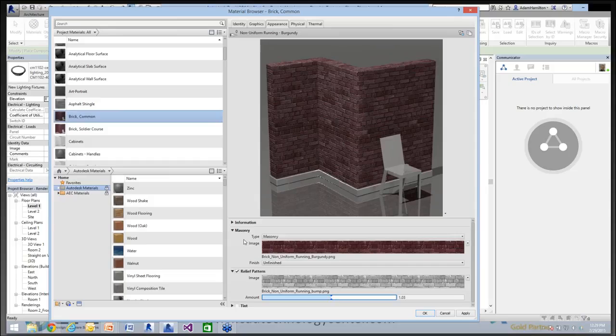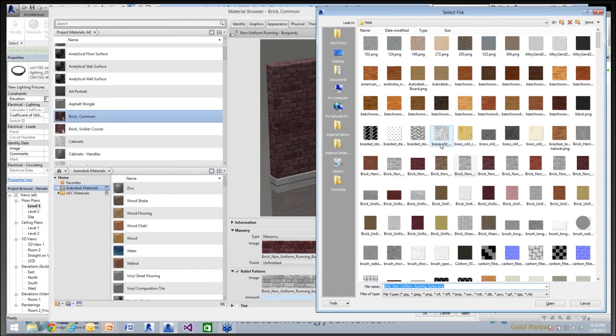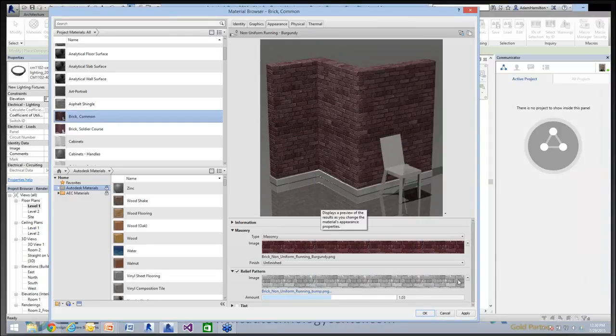And so take that image, and then you'll see the bump. And again, Revit has the default map libraries, material libraries have bump maps in there, and you'll see them tagged with bump. Okay, you see this one has some of the same setups, so the bump map for a lot of these. And that'll give it the texture. So Revit has some of these built in, by the way, but if you need to build your own, you can utilize that.